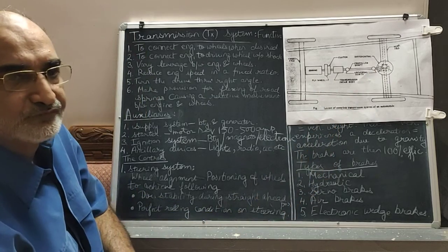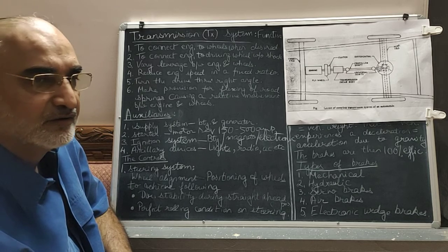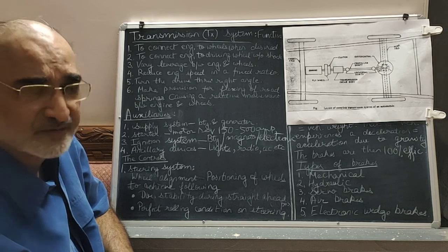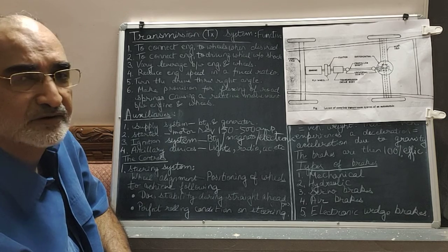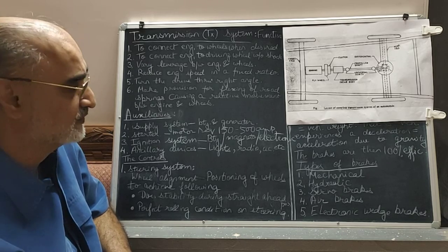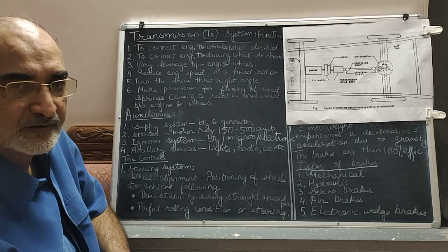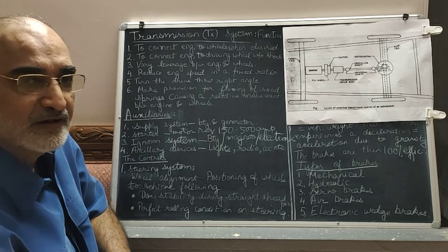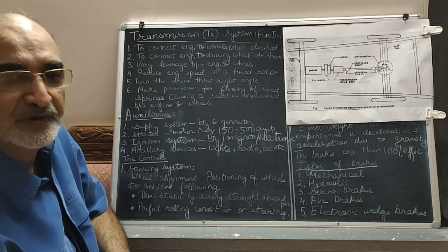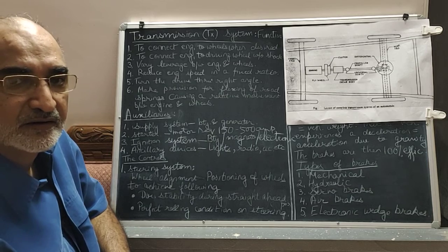The final drive reduces the drive in a range of 4:1 for cars, and the reduction in heavier vehicles, trucks and bigger vehicles, is around 10:1. This is the amount of reduction. The reduction also increases the tractive effort. As we know, a heavily loaded truck, fully loaded, will require a lot of tractive effort to move the wheels initially. So this is helping towards that objective.